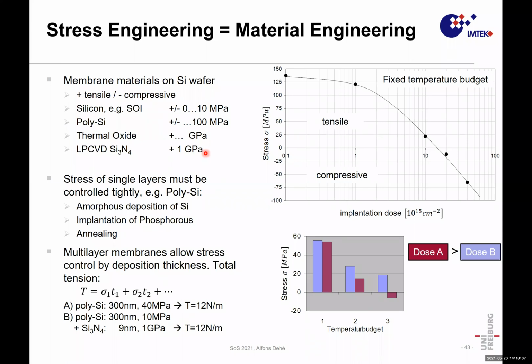Of course, we could make a very high tension diaphragm, metallize it and use this as a membrane for the microphone, or we go to silicon or silicon on insulator with low stress levels. And this is simply a measurement of polysilicon diaphragms. The polysilicon has a special way of fabricating it. The stress level finally depends on the implantation dose or on the conductivity of the diaphragm.